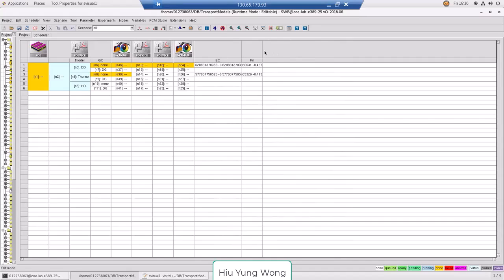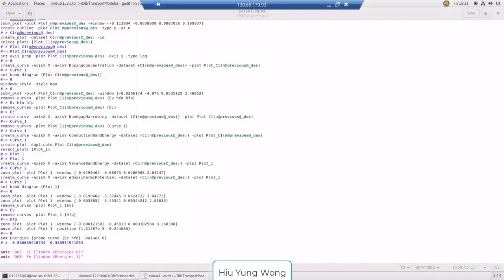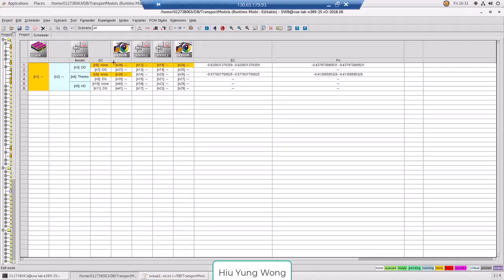Okay. Yes. Okay, but obviously I did something wrong in my code. It gives 2 numbers. Okay, why? It's not that I did something wrong. It's because maybe I'm probing right at the interface. So it has an oxide number and also a semiconductor number. So I'd better shift a little bit. Let's say 1E minus 6, very close to it. Right, and then I run it again.